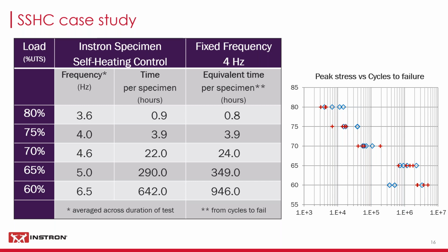And then if it's not heating up very quickly, by contrast, it will take a little step, increase the frequency, little step, increase the frequency, until you start to see some temperature rise. Then as you get close to the target for the specimen, it will allow that to equilibrate. Once you're in a stable state, it will monitor it, and if the temperature starts to rise, once again, it will do quite a responsive reduction in frequency, taking the idea that overheating is very bad.